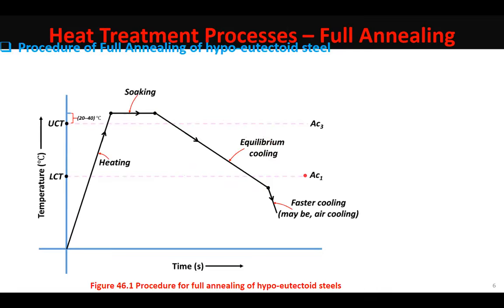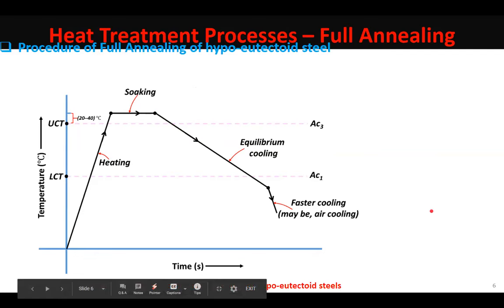For example, generally the small scale industries which we visit, what do they do? They create a bed on the floor, and that bed on the floor is filled with good heat insulating materials like ash, limestone, etc. They are very insulating materials. So quickly you pull out the specimens from this furnace and put them in that bed, right?